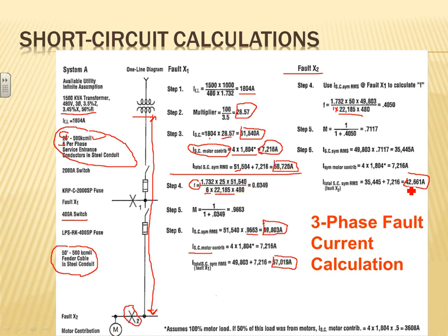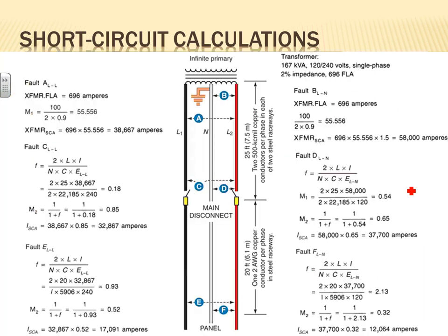I always call it the happy medium. Every time you have equipment closer to the service, you have the advantage of low voltage drop, and the disadvantage of what? High short circuit rating. So the nice thing about having your equipment closer to the service is low voltage drop, like I said, but the disadvantage is your short circuit becomes higher. You might have to go to higher rated equipment because of that.